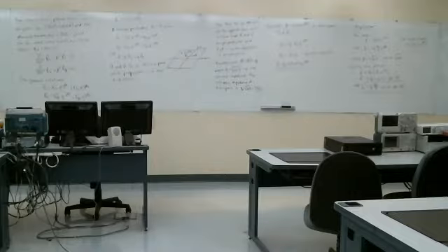It'll be shorter in any media for which mu R and epsilon R are not equal to 1. If you're working with material where mu R and epsilon R are both equal to 1, or mu and epsilon are both equal to mu 0 and epsilon 0, then the phase velocity in that media is equal to c, and the wavelength is the same as it is in free space.